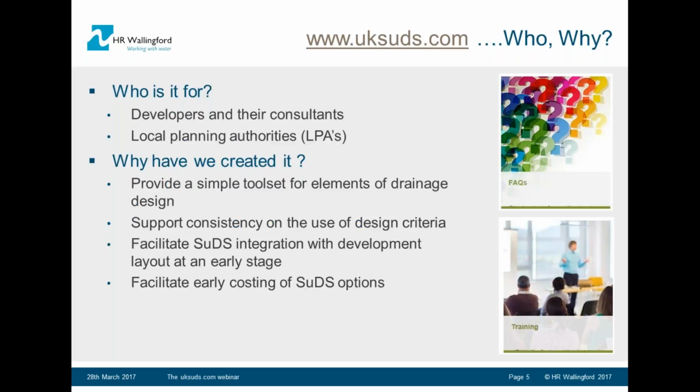So, who's the site for? Well, principally SuDS designers and SuDS approving bodies that will normally be the local planning authority. The tools provide quick ways of estimating limiting discharge rates and storage volumes. This will allow designers to integrate realistically sized SuDS within the initial development layout at an early stage. And that will then facilitate initial cost estimates and option appraisal.